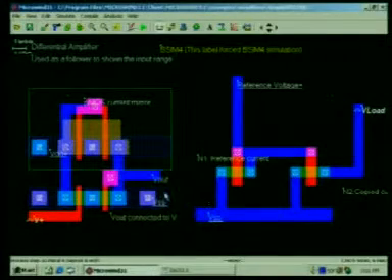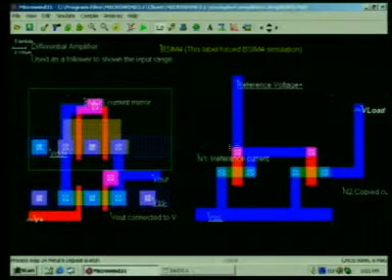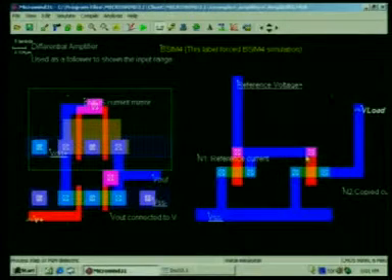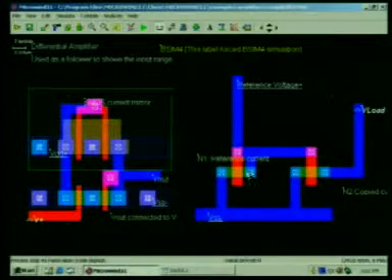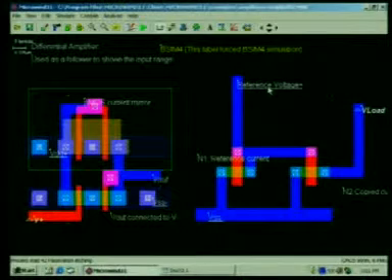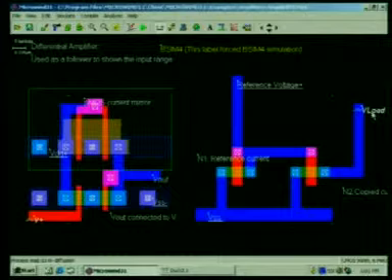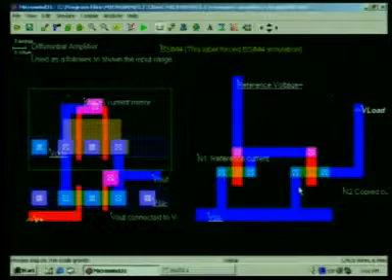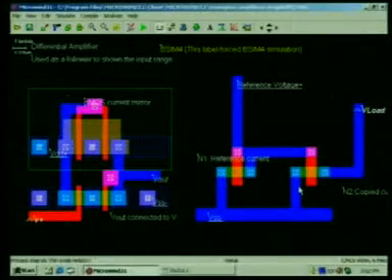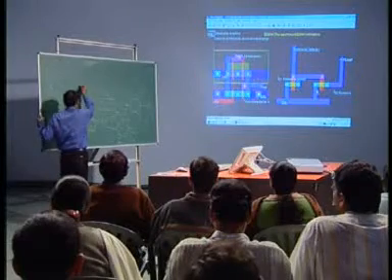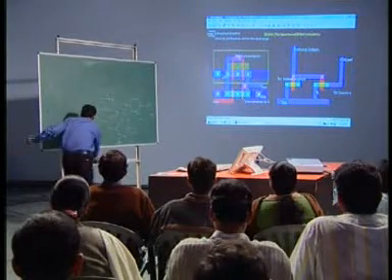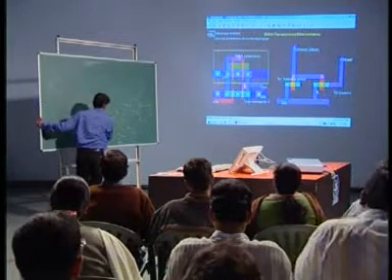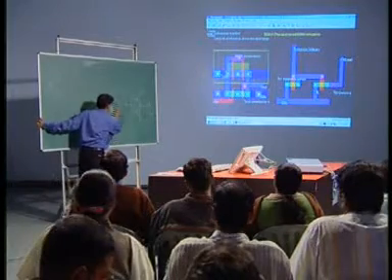See, this is the current mirror. So, this one is your simple NMOS, this is another NMOS. I have just made this common. I have applied here the reference voltage, and you can vary this voltage, and just VSS. That is very simple. I will explain it a little bit, because these are very important fundamentals required for analog kind of designing or any kind of amplifier.